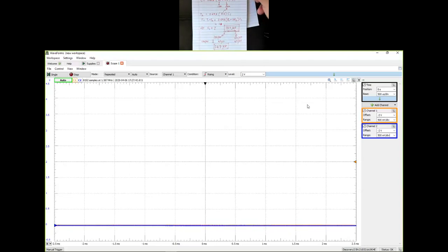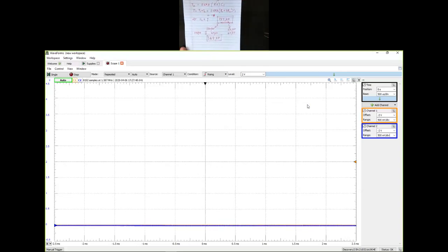Now, you might say, can you get closer than this? Well, of course you can. I could have used more capacitors, like 100 plus 22 plus 10 plus 4.7, and gotten very close, but I did not want to make it more complicated than it needs to be. So I'm using two capacitors to get pretty close, not exactly 1 second, but very close. Those are my design equations that you should take into account. So 147 microfarad is what we are going to put in our circuit.